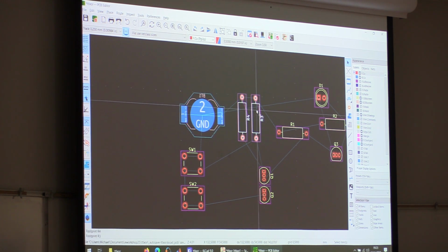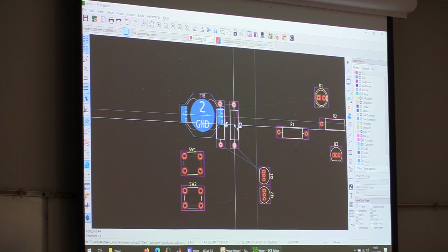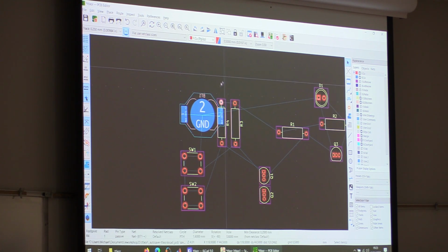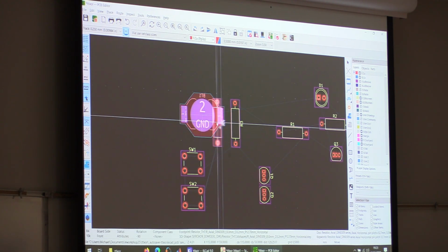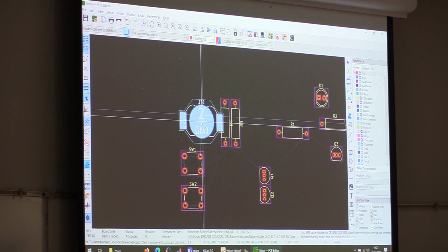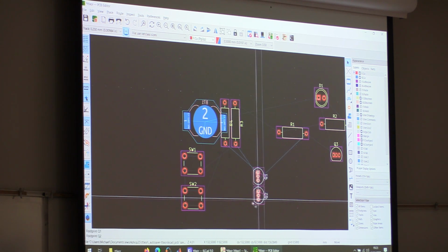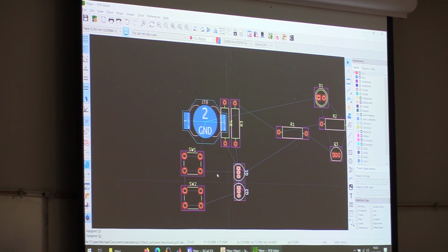However, if you have a component on the back side, you are able to overlap a little bit. Except for that through hole there, that little pin there, if I put that inside the courtyard of that back component, then it'll get mad. So it does help to understand what that component is, and the footprint being that it's through hole, it has both a front side and a back side. So there is that. But I will throw this battery holder right there. These transistors can go right there.